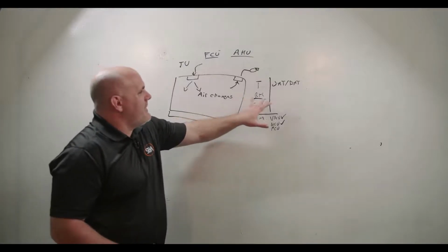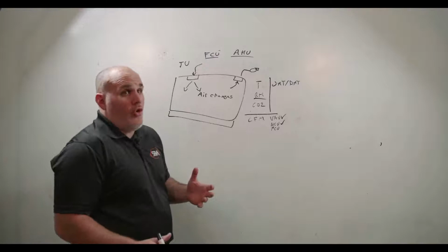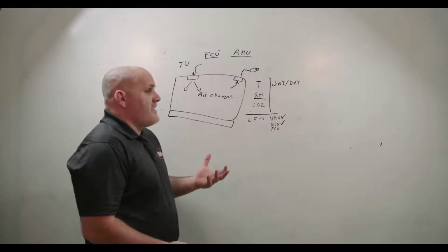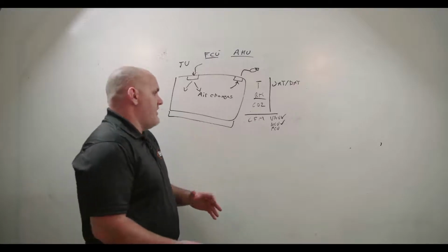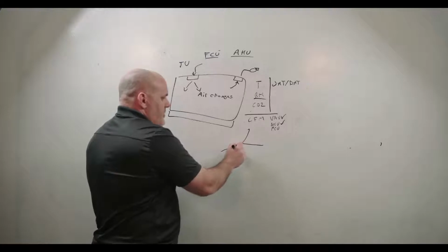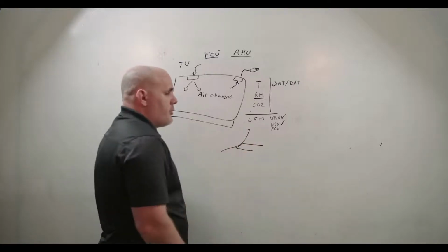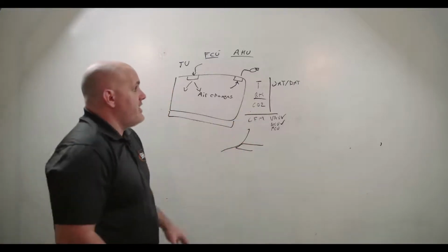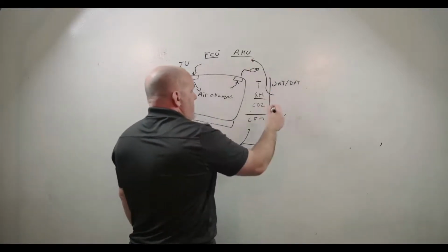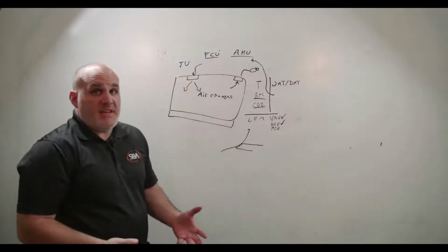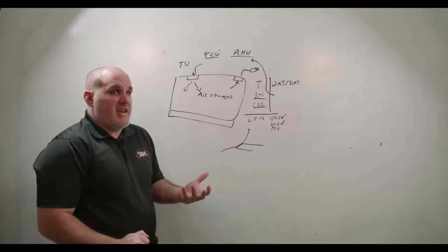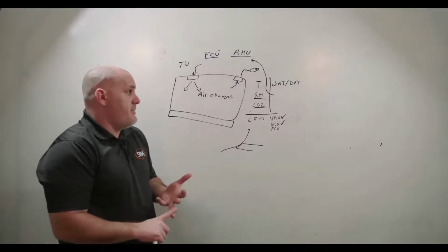Relative humidity, right? That is going to be controlled by typically either a desiccant wheel, or we're going to drive the temperature down to saturation. If you think about psychrometrics, you drive to dew point, you continue to subcool, you warm back up the air, you're at a lower relative humidity. And so we're going to do that with just our humidity control in our AHUs typically. And then CO2 is typically going to be controlled with an outside air damper, and we're going to be modulating that either with demand ventilation or a minimum damper command.